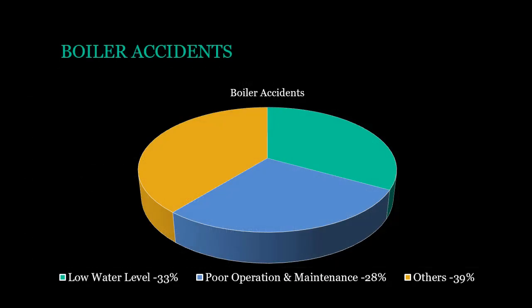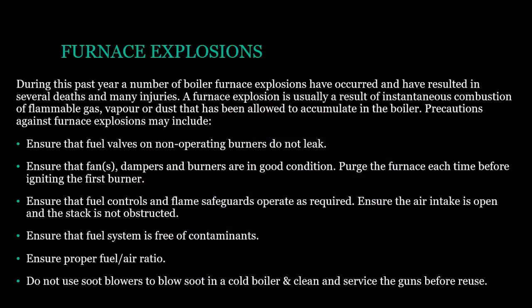Boiler accidents. These are caused by low water level, poor operation and maintenance, and others. Furnace explosions. During this past year, a number of boiler furnace explosions have occurred and have resulted in several deaths and many injuries. A furnace explosion is usually a result of instantaneous combustion of flammable gas, vapor, or dust that has been allowed to accumulate in the boiler.